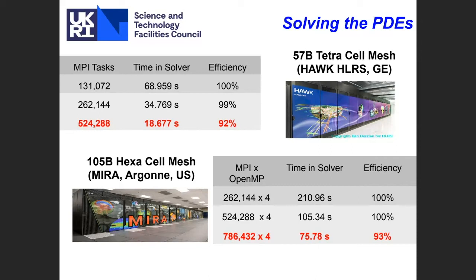So basically that means the code scales very, very well, and this is achieved because to solve the pressure a multigrid is used as a preconditioner and a conjugate gradient is used as a solver, the conjugate gradient being well known to scale very well.